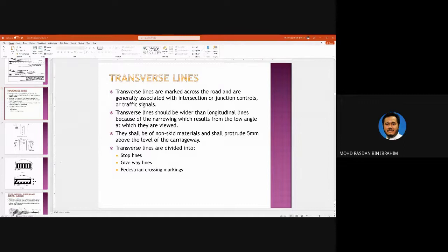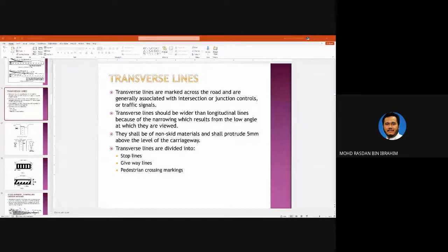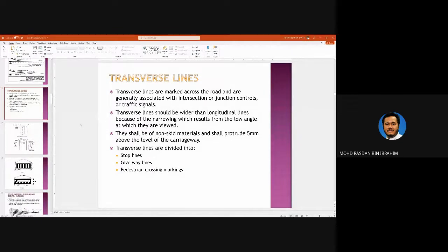On top of that, you have this transverse bar which is supposed to slow down the vehicles. But like I mentioned earlier in our class, in the semester, transverse bars are not supposed to be used at corners because they can be slippery.